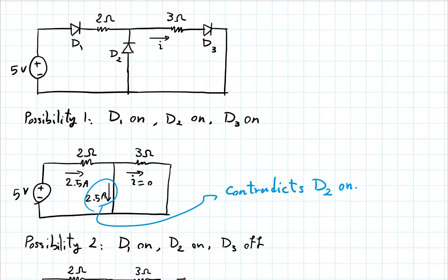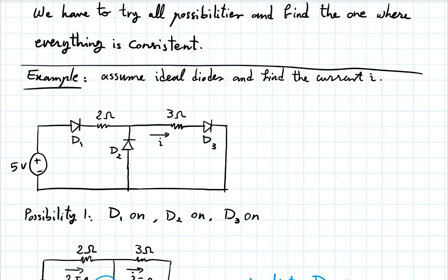What if you're not happy with any of these models and you actually wanted to include the IV characteristics of the diode, the actual exponential relationship? Well, you would, again, write the KVLs and KCLs and all that. For each diode, for the element relationship, you would include that exponential dependence, that formula. And you would solve the entire system of equations numerically, self-consistently. There are standard ways to deal with that. Many of you being in software or interested in software, you could write a small code as an exercise to solve a circuit like this with an actual exponential formula for the IV characteristics.